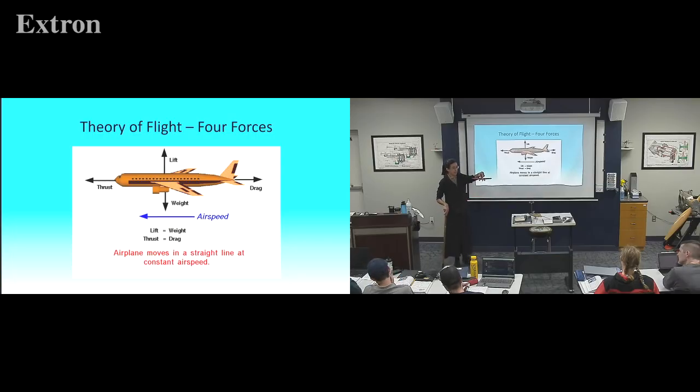But let's say I'm at 10,000 feet and I have a good long way to descend. After I initiated my descent, now I'm going at 100 knots at a 500 foot per minute descent. Is thrust again equaling drag and lift equaling weight? It is, because now I'm not accelerating, I'm not changing direction, and I'm not decelerating.